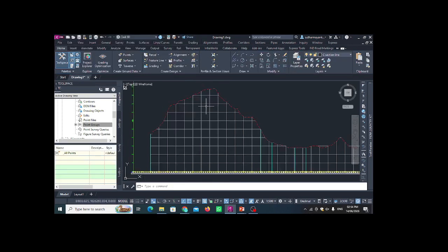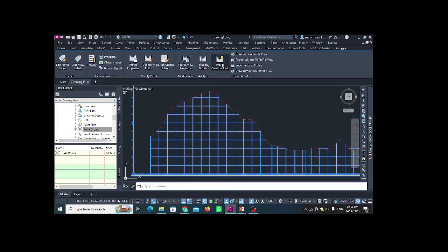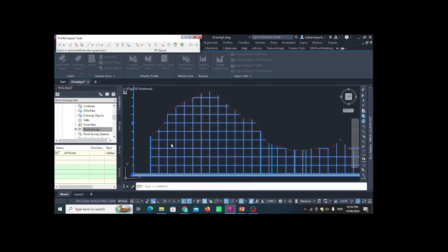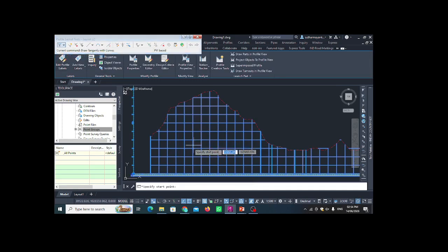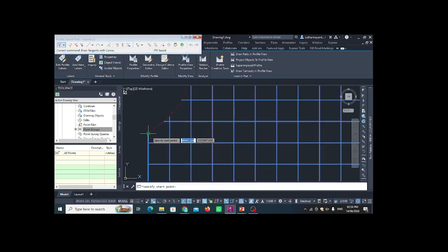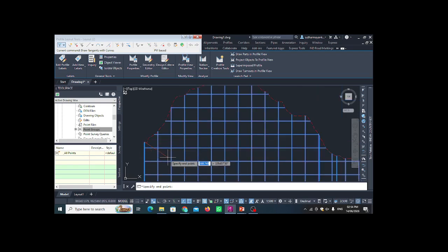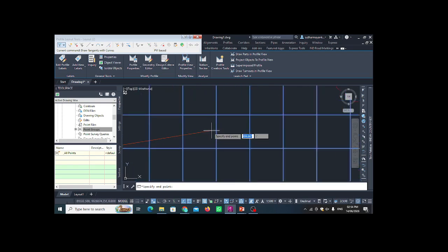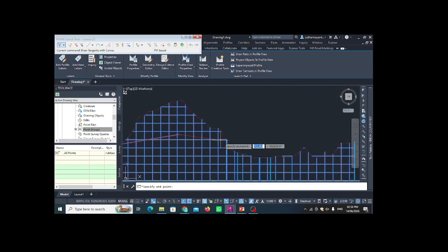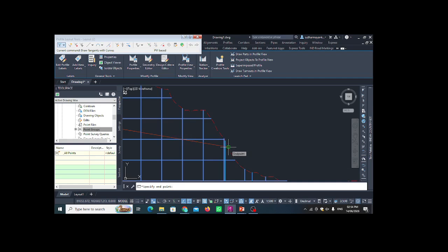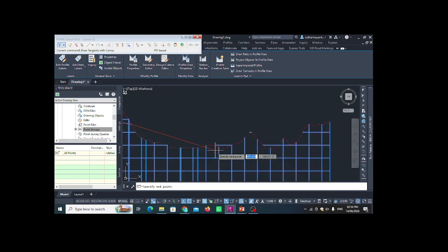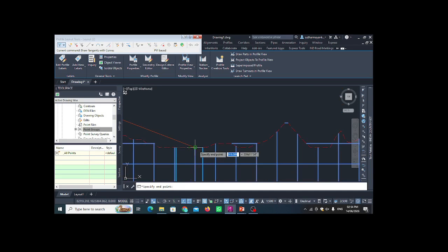See, the same way you create your alignment, the same way you have to create this alignment. Okay. So now what I do, see, first I click here at the first point, and then I have to click here, and the third part I am going to check here. So we have to manage the minimum and maximum PVI station.